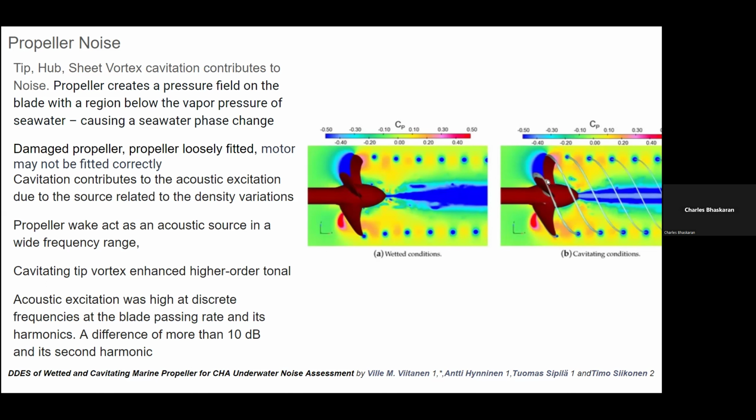You could see there's turbulence happening in there, and the hub of the propeller also creates the wake. So the tonal components we talked a little bit about are coming from the tip, and mainly the broadband is coming from the hub, vibration or whirling happening in the hub. There is a phase change that happens. So it's two different densities in the water. When air comes in, that makes a lot more noise, right?